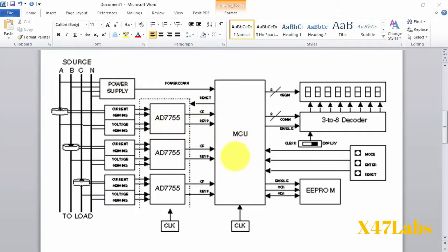We can do the programming as custom programming, and here are current transformers 1, 2, and 3. So three current transformers get the three phases A, B, C, that is phase 1, 2, 3, and N is neutral. So you can get the three phase plus neutral, that is a three phase 4 wire system here.